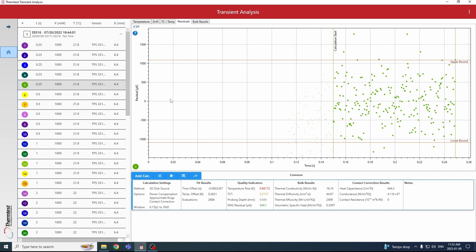And we can compare that to the thickness and select which one is the smallest dimension. The TPS software does this automatically, but it's good to understand this concept. So the available penetration depth from the edge of the sensor to the edge of the sample is 13.6 millimeters, and the smallest dimension from perpendicular to the face of the sensor is 20. So our smallest dimension is 13.6 millimeters.